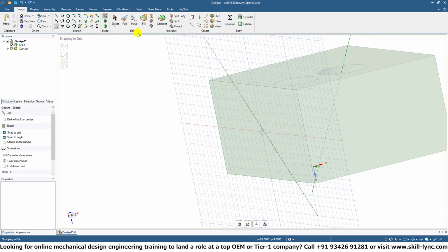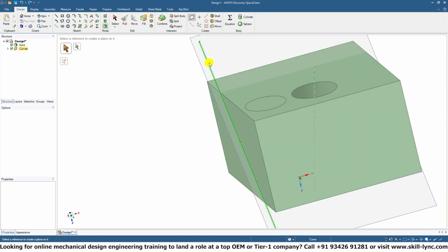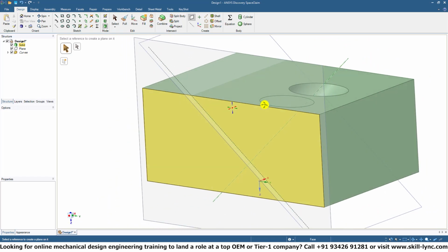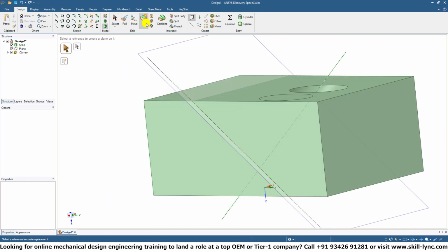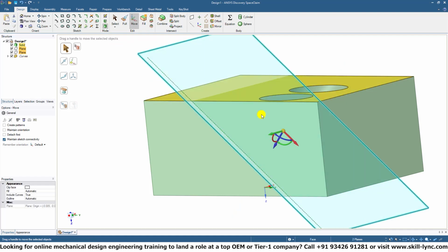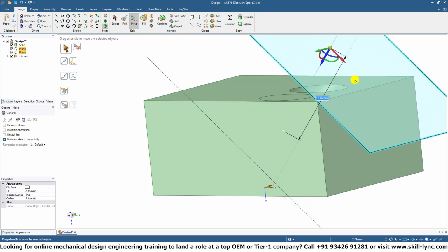If it allows us to create that, we'll go back into 3D mode, and when we select the plane, hopefully it gives us that intersecting plane. I believe you can even move planes using the move tool. There we go, I just didn't select the plane for some reason. Can move it out over here.